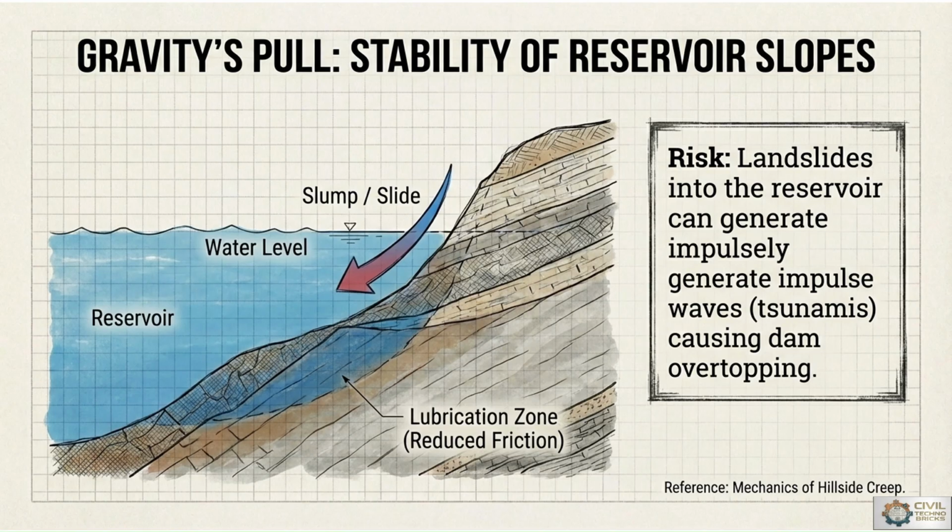Geological investigations assess slope angle, rock discontinuities, rock characteristics, and weathering conditions. Stabilization methods include drainage systems, retaining structures, and slope reinforcement so that we can stabilize the reservoir slopes.